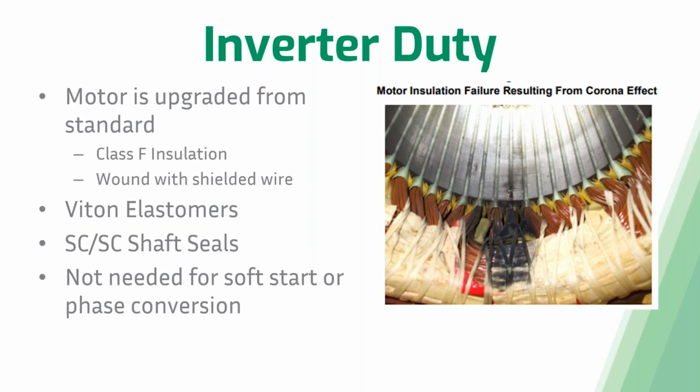Also with inverter duty motors, you're going to get Viton elastomers and silicon carbide shaft seals. That's really just to further increase the life of that pump. Now, one thing to note is that with inverter duty motors, you don't really need them for soft starting or phase conversion. You only really need inverter duty motors when you are actually varying the frequencies frequently.